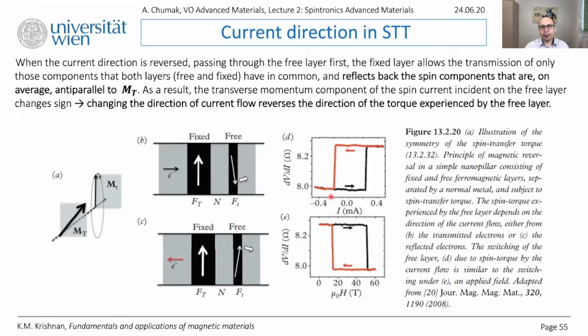And then you have originally this state, and you start to apply current in one polarity. What happens if your current is large enough? Your torque term is proportional to current, so at some point you will apply large enough torque in order to switch magnetization. And then further increase in current changes nothing. But let us look at what happens if you then decrease current to this point. Then these 2 layers are just parallel magnetized, and that's it, like it's shown here. They're parallel magnetized and everything's fine.